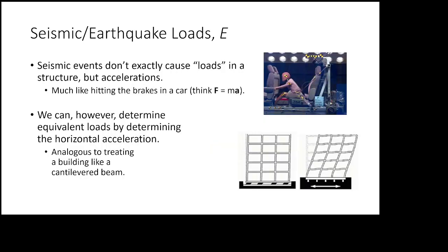Now, one of the things about seismic events is that there is no earthquake monster pushing on the building. It's not like snow or dead loads where there's actually a force applied. The load comes from the building's own inertia, okay? Now, it also changes how we as structural engineers handle these types of events.